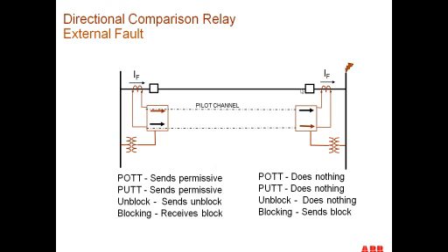The reason for this is we never want to overtrip the relay and trip for a fault external to the line or on the bus. So we can do some things instead. We can set an element that looks past the far end of the line from one end of the line, and then we can set another relay looking from the remote end of the line back toward the other end through the line also.